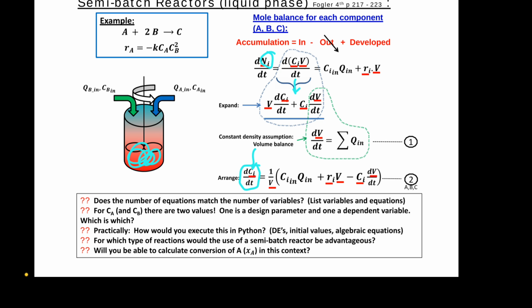So in this differential equation, just rewrite that in terms of concentration and the volume, which will also change with time. Apply the product rule to write that in terms of the two differential equations, and then combine, rearrange to make that the subject of the equation. And remember, this is the one that we've just derived from the mass balance, but assuming that the densities are not only constant but equal.